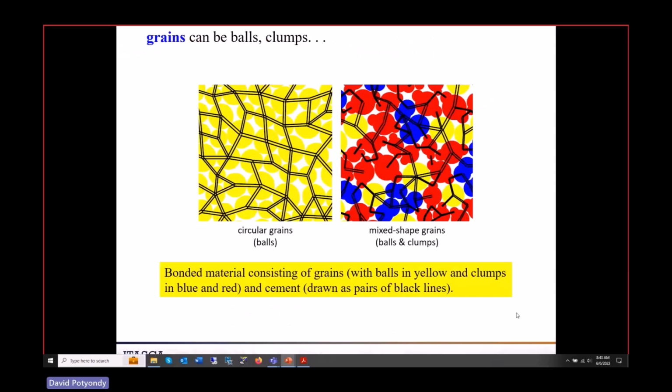So here's the idea. I'm going to show grains yellow here. This is just discs glued together. Every time there's a parallel bond, I'll do a visualization. I'll just draw two black lines from center to center. So this is the bonded network, parallel bonded network. This is the collection of clumps. I have three shapes. I have disc shaped, I have two overlapped shape, and I have this weird three overlapped shape. And using all the same stuff we've done, instead of doing ball generate, I say clump generate. I can generate packings of these things.